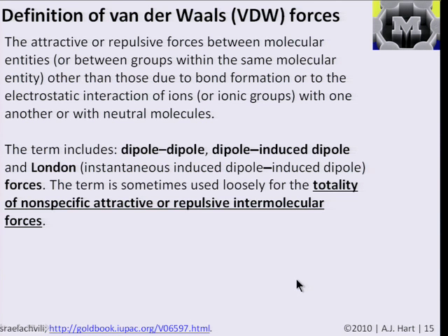And formally, this includes the interactions between dipoles and induced dipoles, and what are called London forces. And basically, we don't need to know all that goes into the van der Waals forces, but we just need to accept it's something that exists. Based on the properties of a material, knowing a particular constant called the Hamaker constant, which we'll learn about later, for say a metal or a ceramic, and based on the geometry and the knowledge of the law of how the interaction decays with distance, we can very accurately calculate these for different shapes.